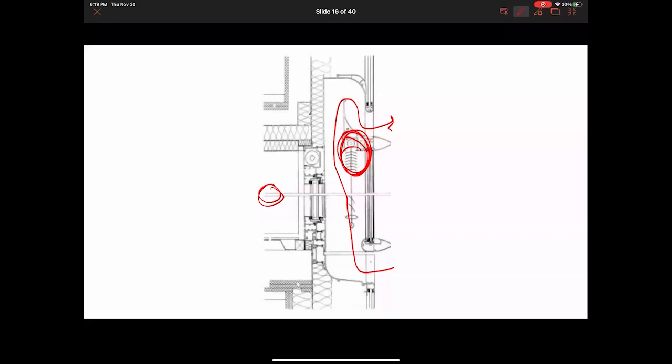And again, it's just like when the sun's out and your car is parked. How hot does your car get? Even on a not that hot day, it may only be a 75-degree day, but if it's sunny and your car is facing the sun, it could easily be 110 degrees inside your car. That's a huge amount of BTUs per hour coming into your car. Well, that's coming into your building too, if your building is all glass and it's heating up your building. And so we would like to shade the building.